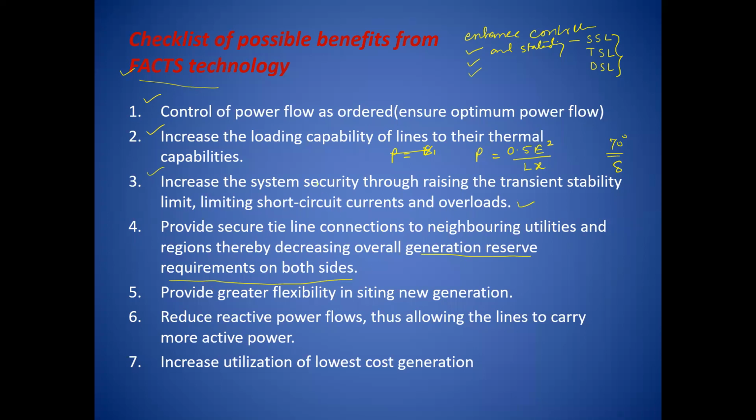It means that suppose we are operating the system independently. Maharashtra is operating independently, Gujarat is operated independently. Definitely in Maharashtra, we have to keep some reserve capacity under some contingency, like there may be a failure of one generator. Suppose the Deepnagar power plant has failed, therefore there should be some reserve capacity in Maharashtra to provide the power during that failure situation, isn't it?